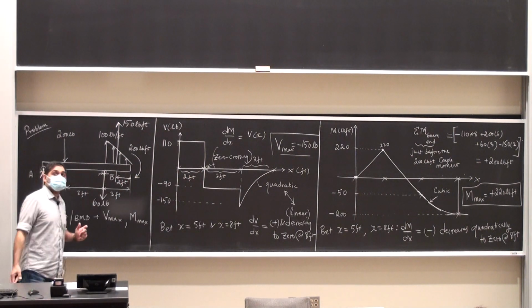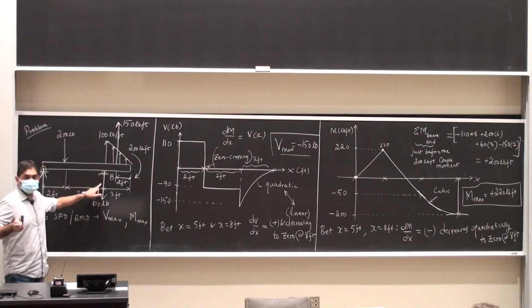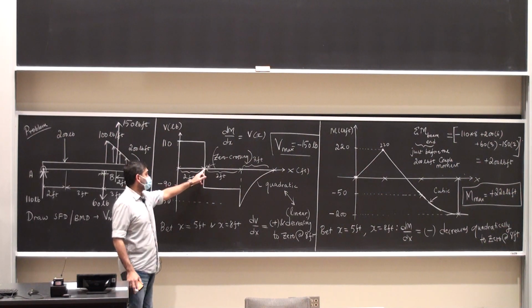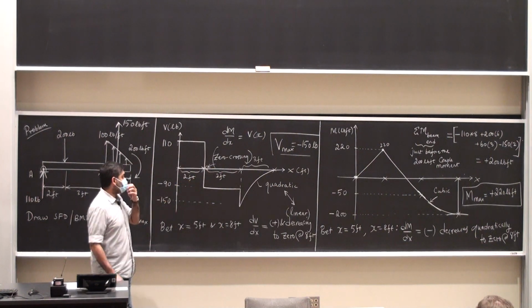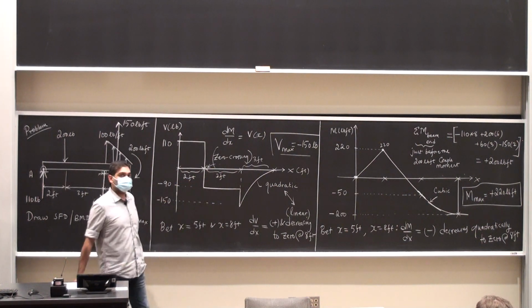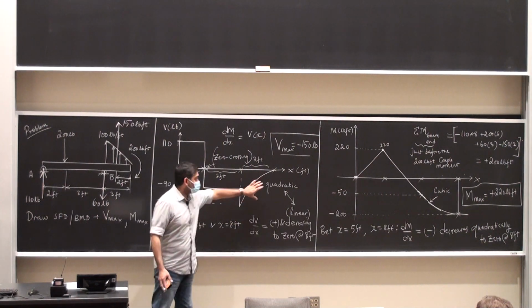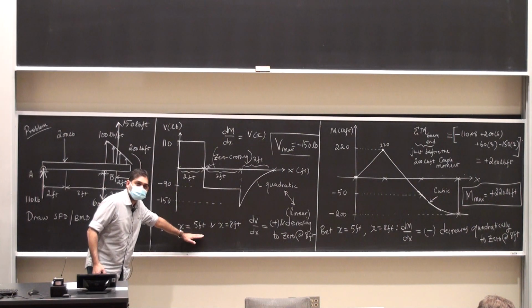When you draw the shear force and bending moment diagrams, let's say in an exam, what are the things I need to see? I need to see the support reactions calculated, first step. Then, if there is a point of zero crossing, label that. If there are pieces that are not regular, which means there is a quadratic or a cubic, then tell me how you obtained this quadratic by showing how the slope evolution took place.